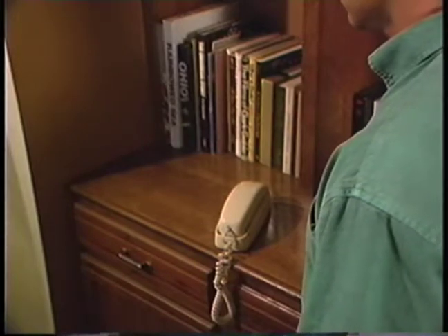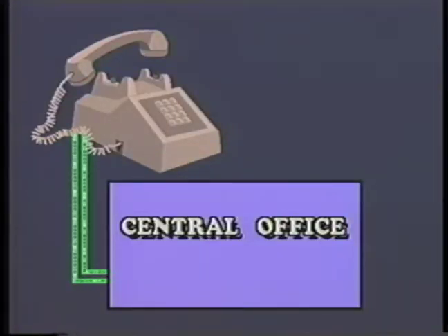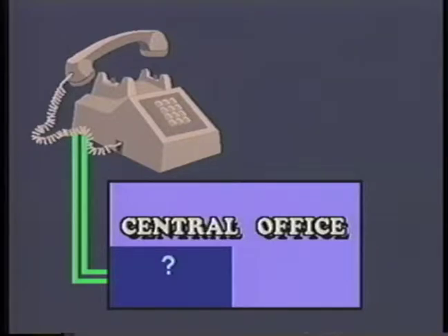The first step in call origination is when you pick up the handset. Now, a circuit is completed between the telephone set and the central office equipment. As the switch monitors the lines, it detects the completed circuit. This is called request for service. If the switching machine can handle this request for service, dial tone is sent to the person's receiver.